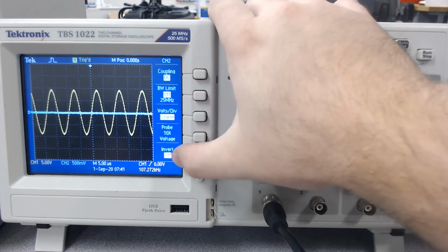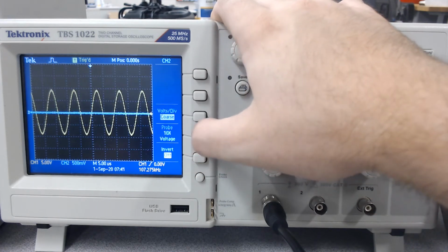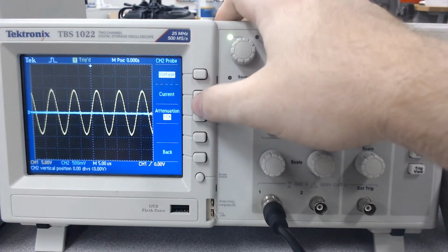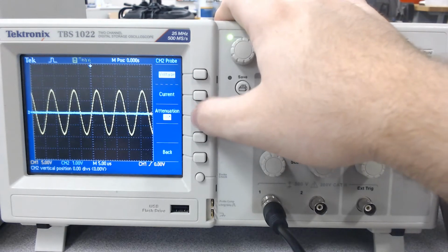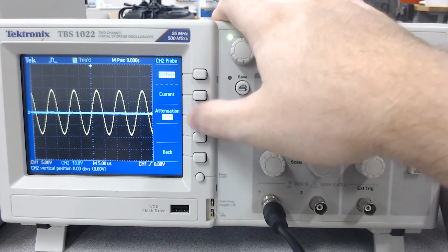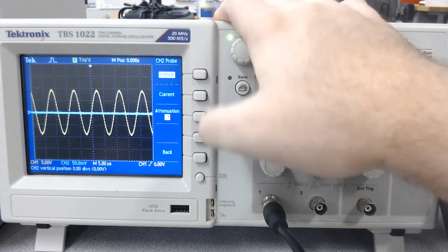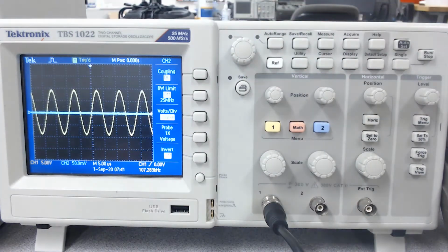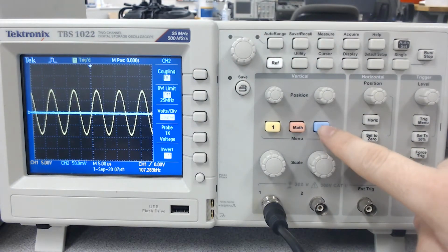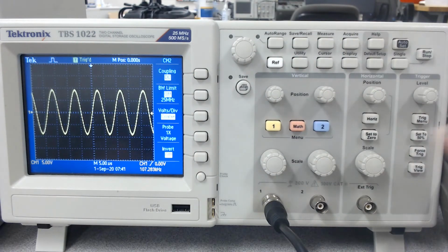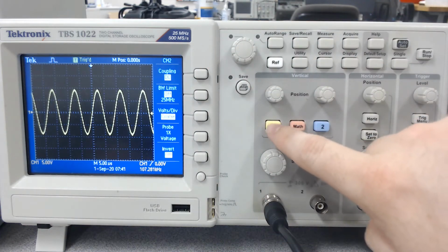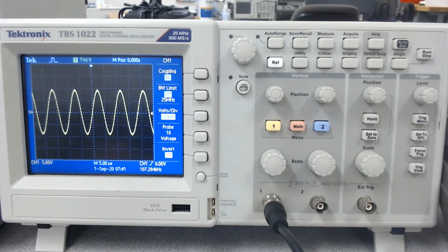So we hit the probe 10 times voltage. We cycle through. Again, there's a little bit of a delay, so it cycled through and actually went past 10 times. So I'm going to have to do it a little more slowly and get the attenuation 1x, hit back. It now has that blue line. Since there's nothing coming into this signal, it reads all zeros. If you just hit the 2, it disappears completely. These, again, are blue, so these are all channel 2 information. You don't really want those, so if you hit channel 1, you can see it that way.